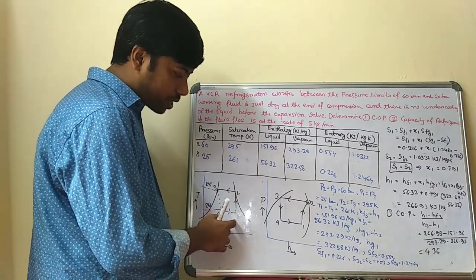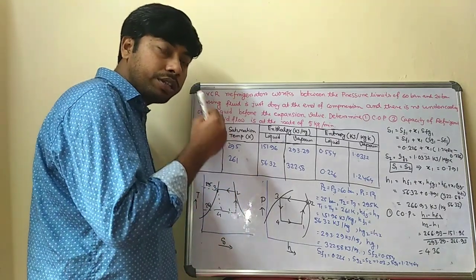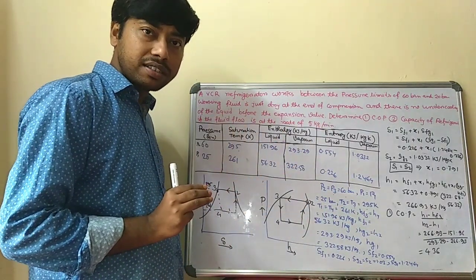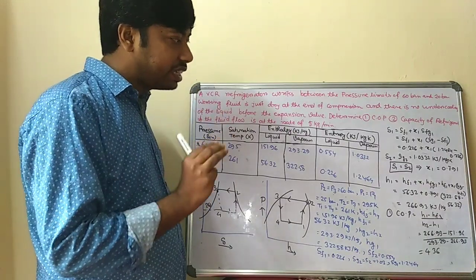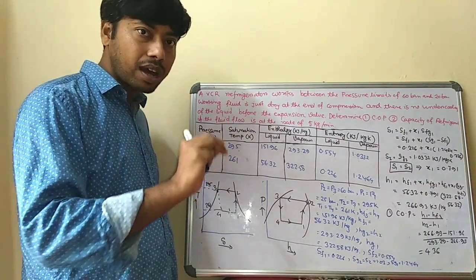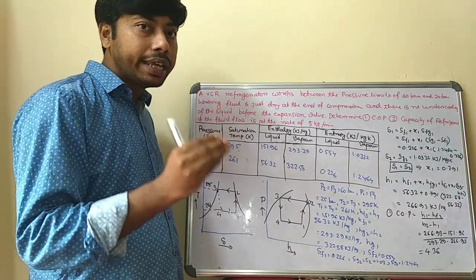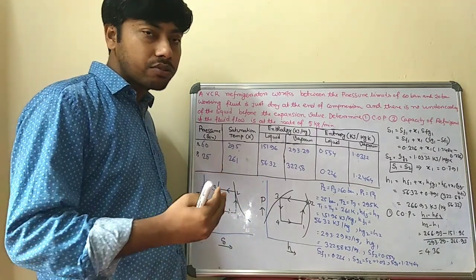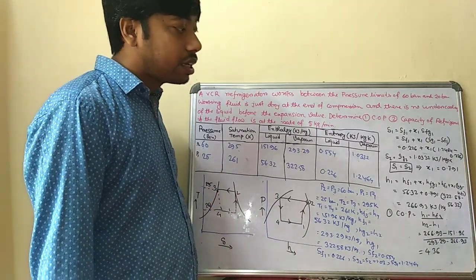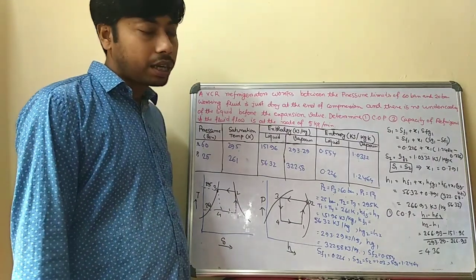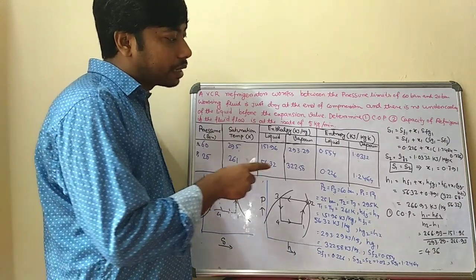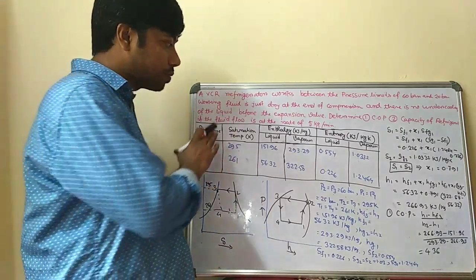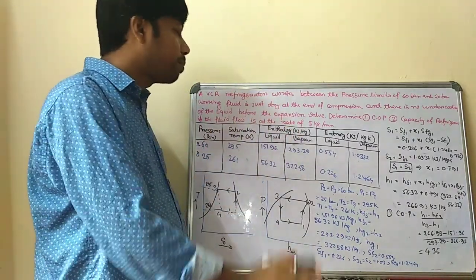Now, state one is in the wet compression region, meaning the liquid-vapor dome zone. So when you calculate the enthalpy, there are liquid properties as well as vapor properties. So H1 will be HF1 plus X1, the dryness fraction, into HFG1. So put all these values, X1, HF1, HFG1, then you can calculate H1. Put these values and you can calculate COP. COP will be 4.36. So this is the coefficient of performance for a particular VCR refrigeration plant.